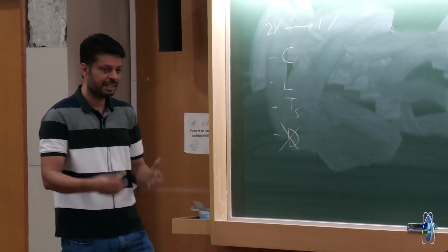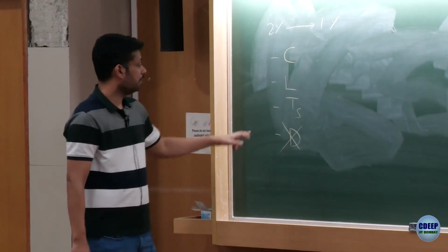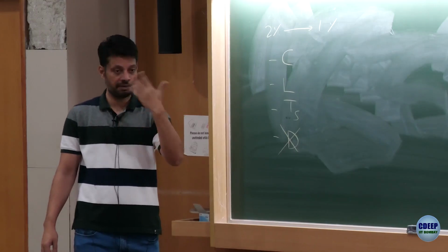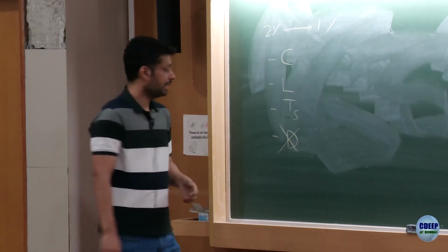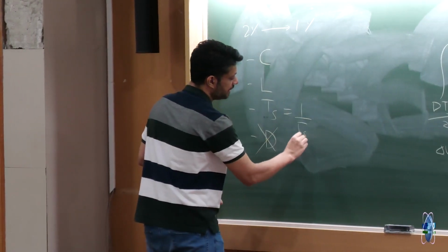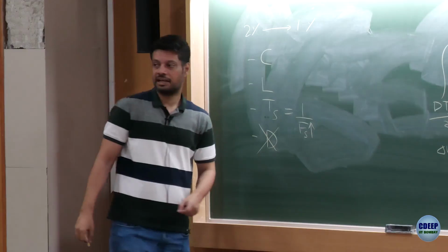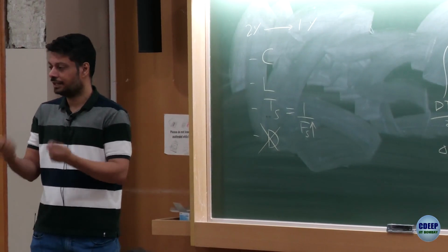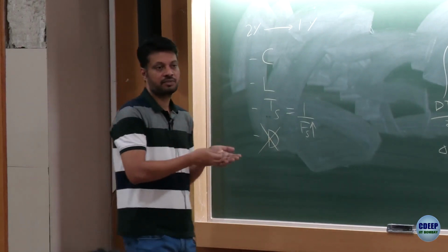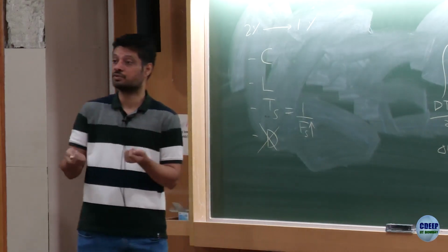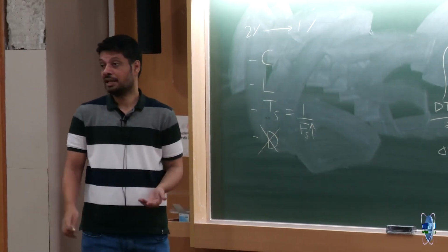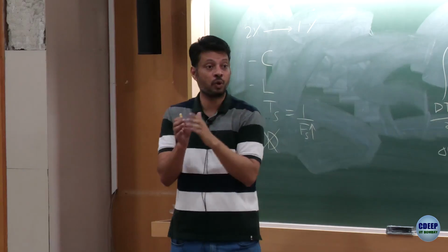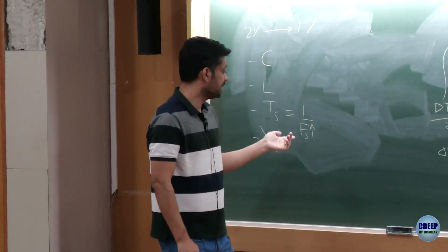Yeah, of course, D you have to maintain constant. You can change Ts if you want. Will you increase Ts or reduce Ts? Reduce Ts. That means you will increase the Fs, which is the switching frequency, right? If you have to increase Fs, what is the implication of that? Switching losses will go up because now you are switching more frequently. Higher Fs means more cycles per second. So maybe you would do that if you are okay in reducing the efficiency a little bit, but you don't want the size to become more, then you would increase Fs.